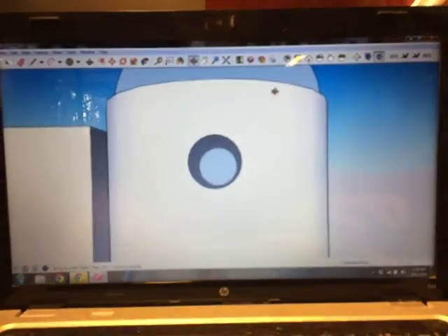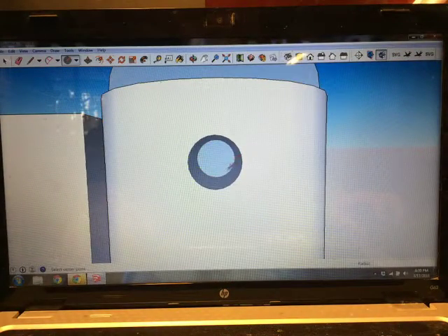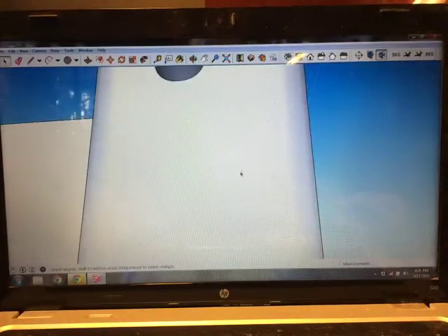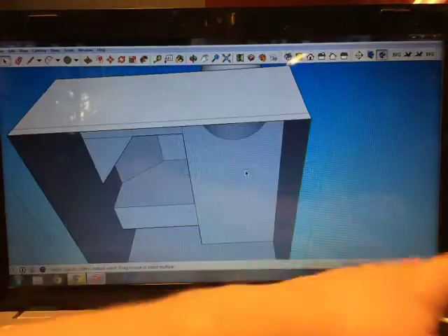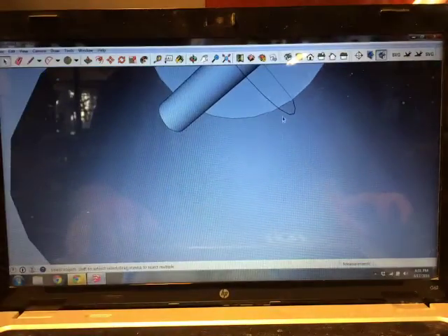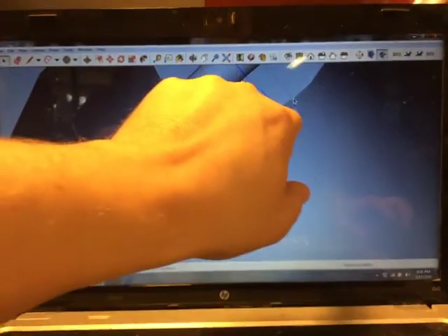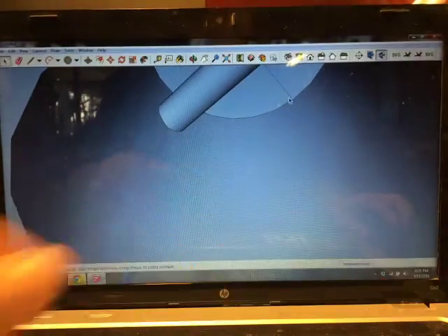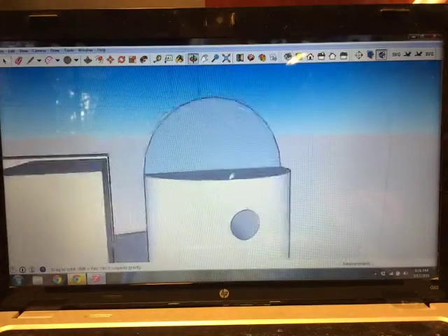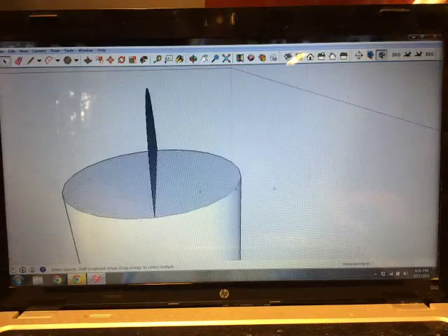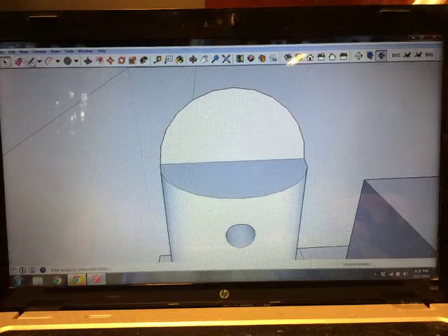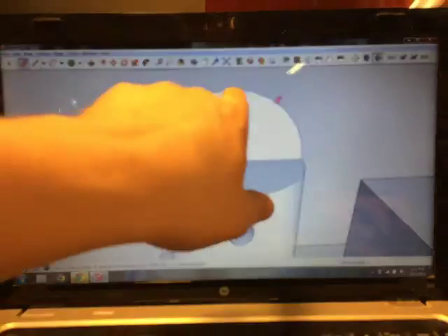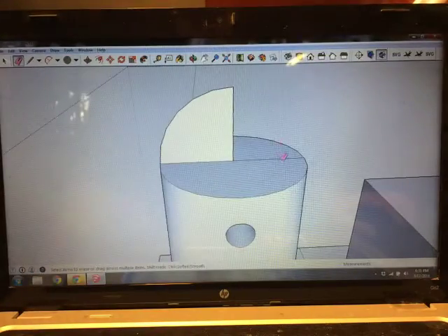Now that may do stuff under here too, but if that bottom piece isn't connected, then we should be able to delete that. Now we just deleted the face, which means inside here there's still a thin little rim. Yep, see that rim in there? Since this is a line segment or a group of line segments that ends at an endpoint, you can delete this without worrying about deleting the top. So this top piece wasn't deleted. So here's what we're looking at. Now here's what I often do. I'll bisect this and then delete just the outside. Well, if this outside's gone, the face can't exist, so it'll delete the face as well.